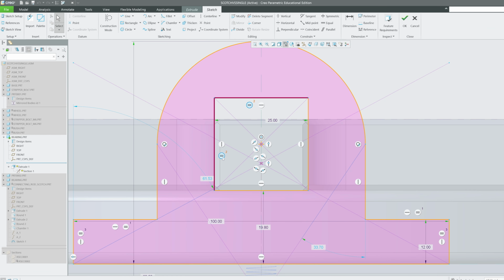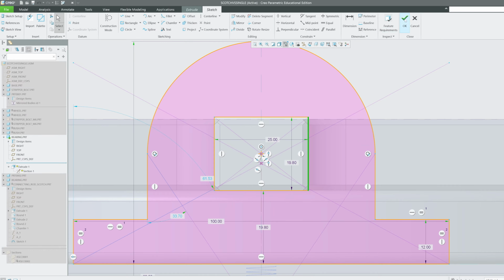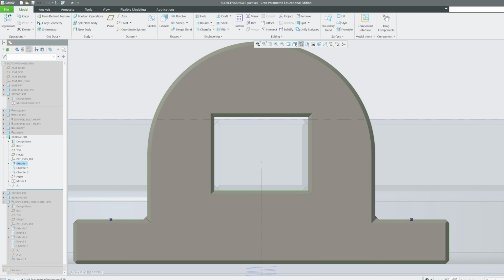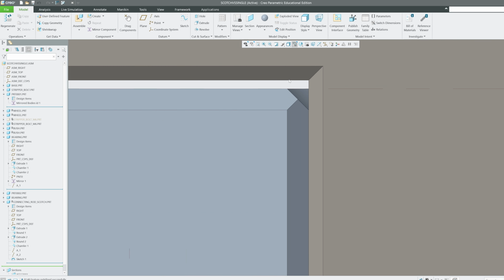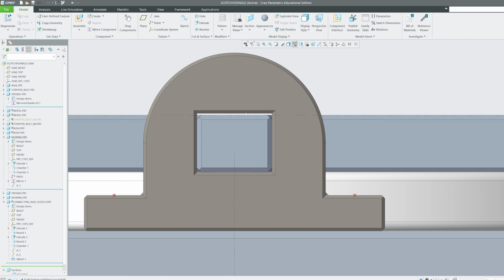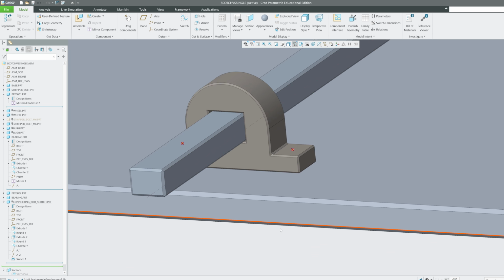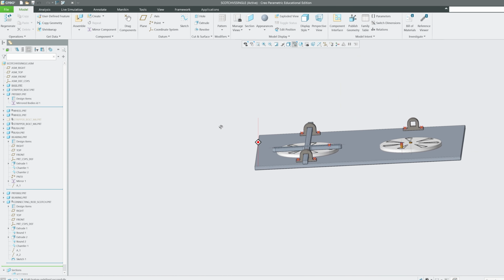Let's delete this actually. It's not needed. Now I need to reduce this to 19.8. Let's click OK, and then OK. Now I think in terms of height it looks good. Yeah, so it was actually 19.3, but it's okay, I'm keeping some clearance here.